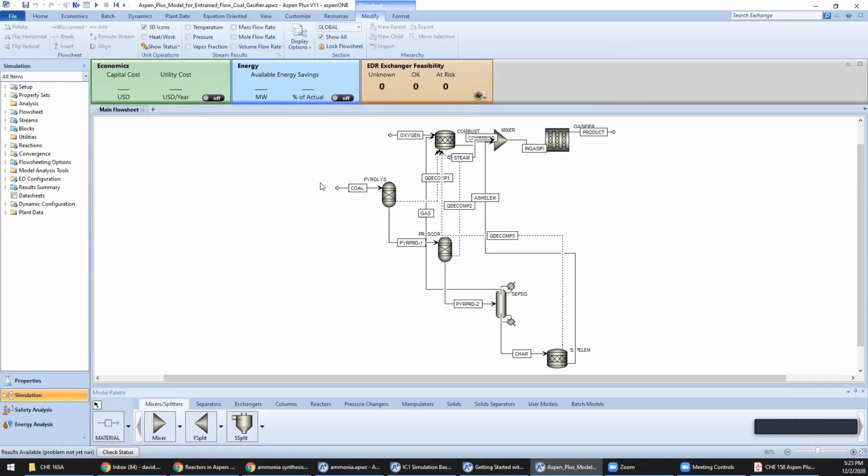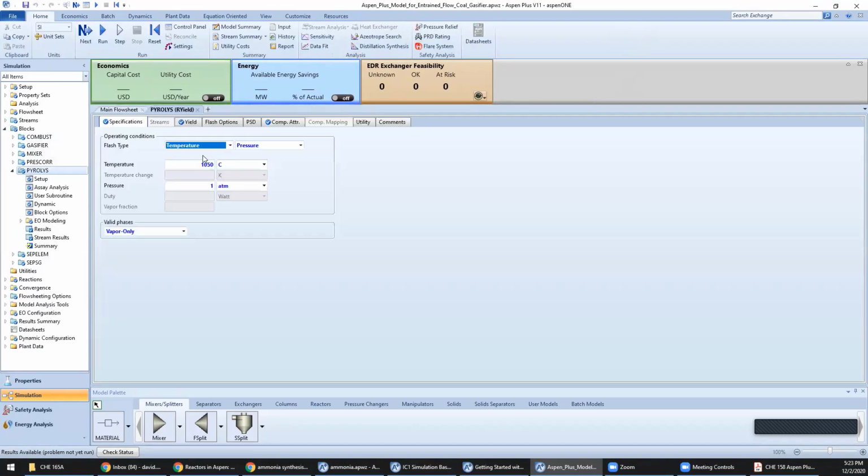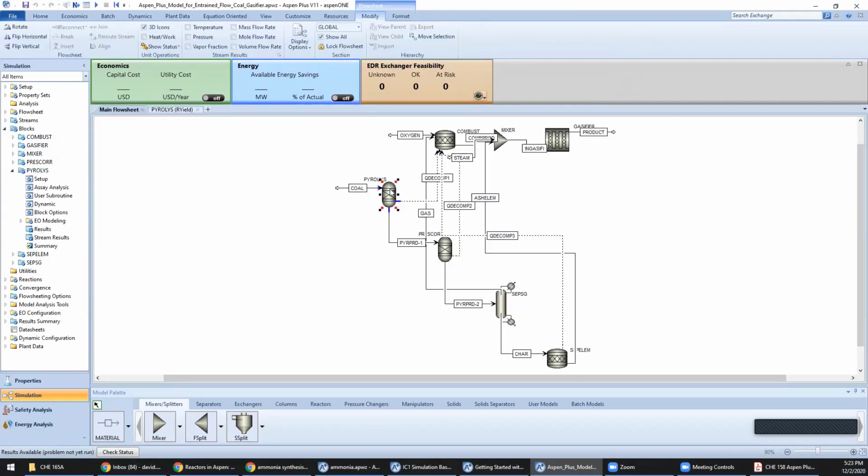So you have coal coming in in this case, as well as oxygen. Now, in the physical system, they're coming in the same port. But here you have the combustion reactions being taken care of. Here you have endothermic pyrolysis reactions being taken care of in a, what block is that? Equilibrium, I think. Oh, a yield reactor. So a yield reactor is taking care of your pyrolysis reaction, your endothermic stuff.